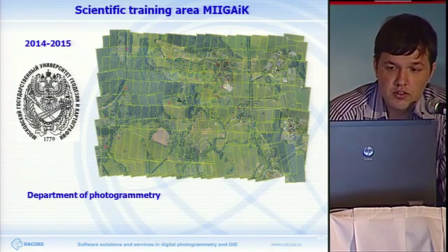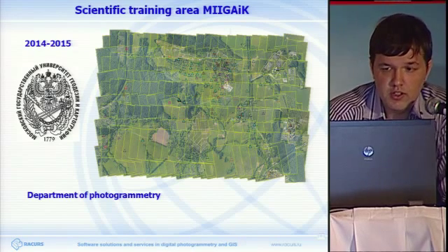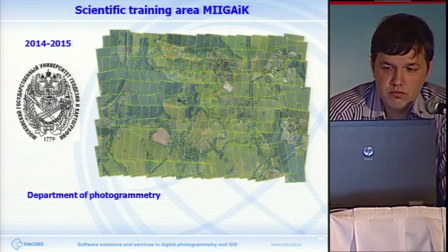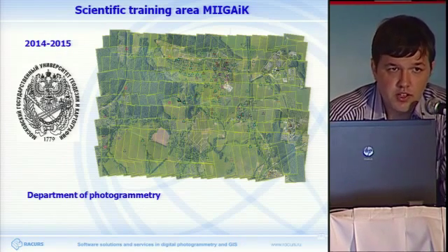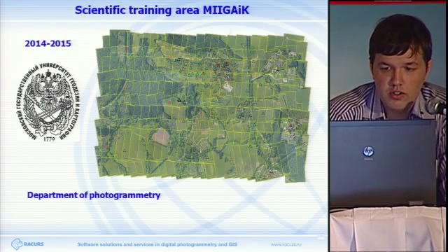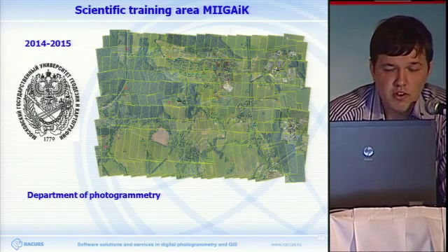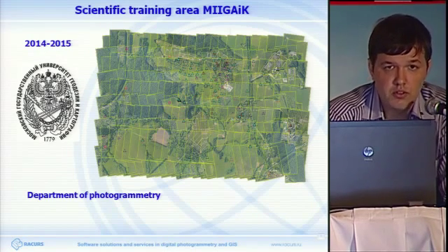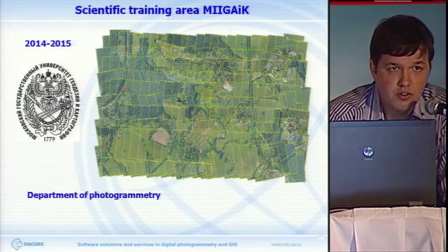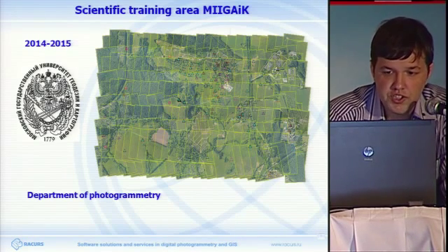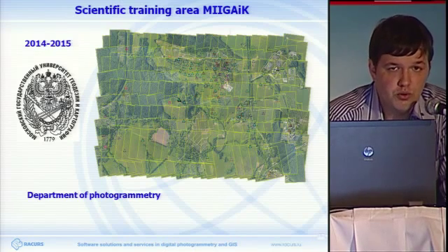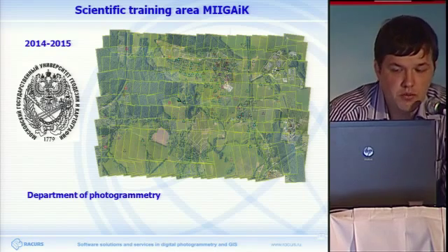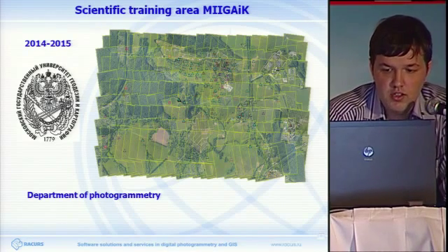The calibration of cameras is done in two stages. First, laboratory calibration and field calibration. At the same time, laboratory calibration implies stationary conditions, but stationary conditions for the use of consumer cameras are not efficient, because when using a consumer camera in the air with the random photography by the UAV, in fact, all the camera parameters are distorted because of external factors. That's why field calibration would be the best process.